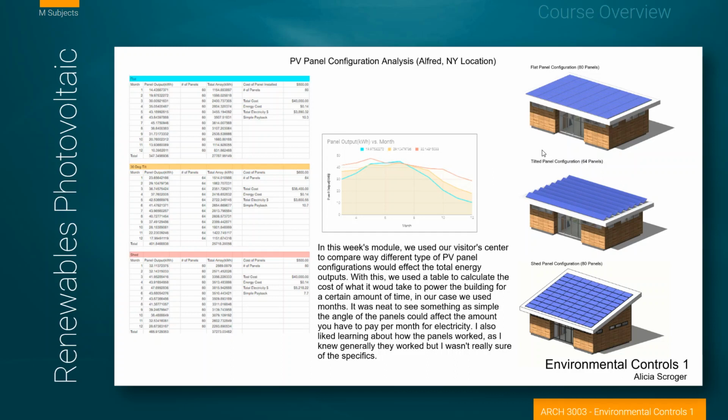In renewables, our project was to actually place photovoltaics up on the roof, and we looked at various configurations for the performance of them. We have a flat roof. We put flat panels on. They didn't have optimum orientation, so we did an analysis where we used software that would allow us to generate the output of the panels, and then compare what we were assuming the costs would be, and then looking at simple payback based on the amount of energy they produced.